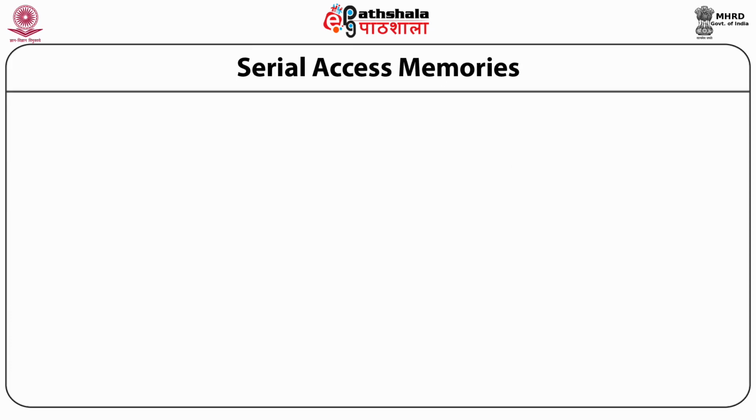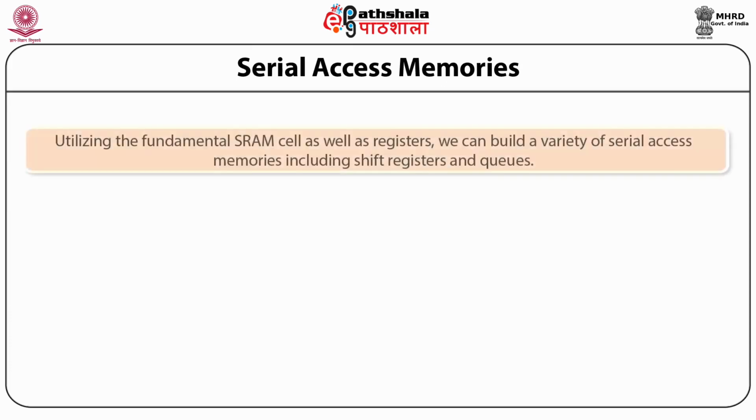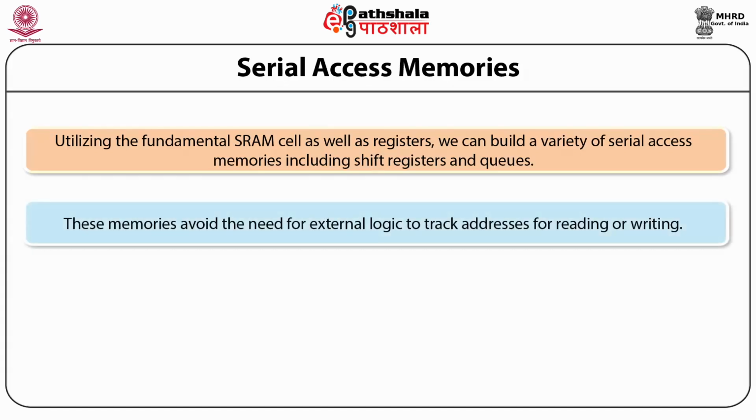Now let us discuss the serial access memories. Utilizing the fundamental SRAM cells as well as registers, we can build a variety of serial access memories, including shift registers and queues. These memories avoid the need for external logic to track addresses for reading or writing.